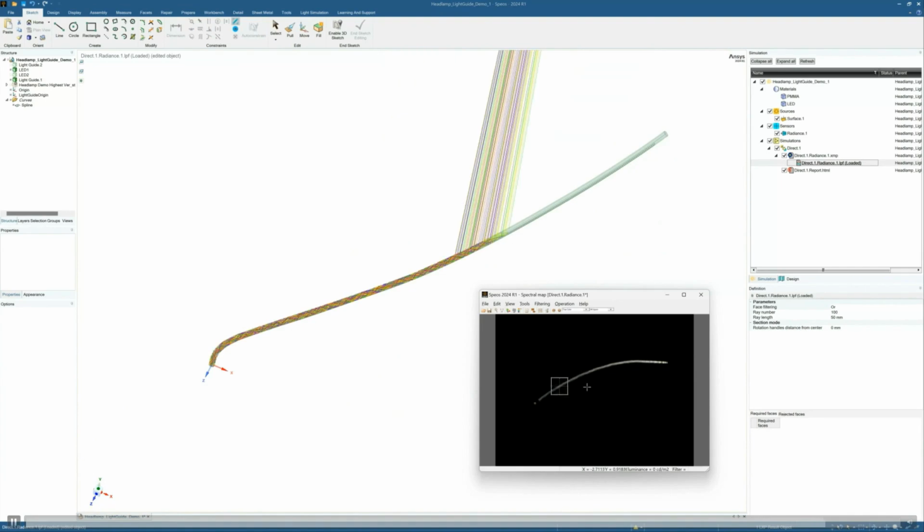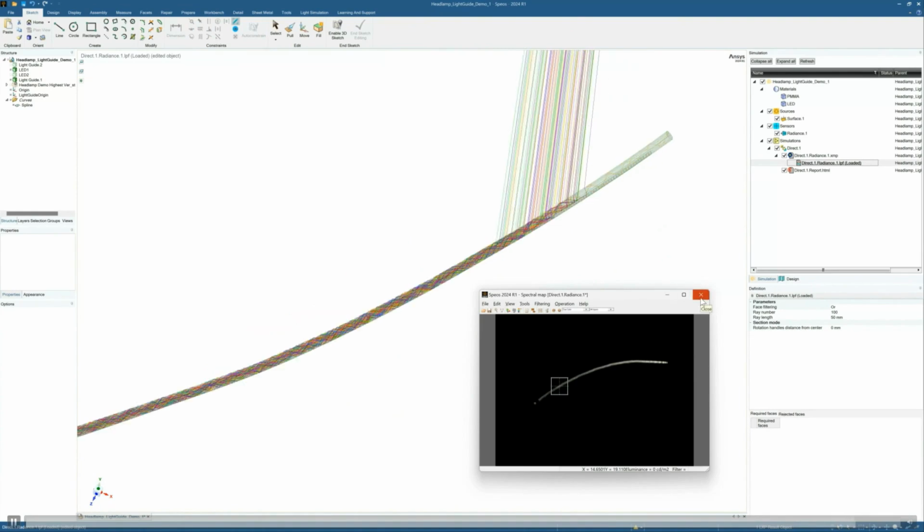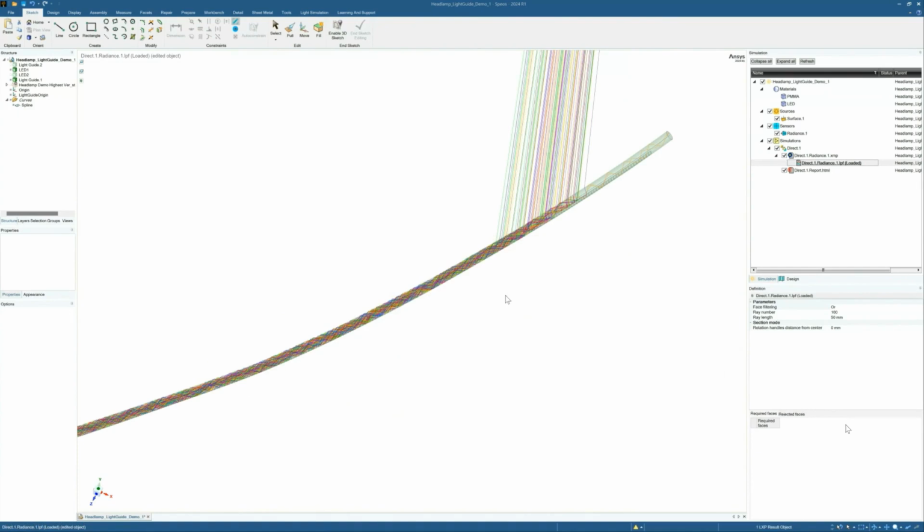You are also able to change the ray numbers. There are a lot of rays being shot through the system right now. You can pare that down to just a few, or change the ray length as well. So I think that's it for that. That's what I was saying right here in this section: this ray number and ray length is just for your imaging purposes, just like how that source was. It doesn't have an actual impact on the simulation itself because it's still shooting through 2 million rays. But if you wanted to get a better idea of what was going on and not have an entire mess in here, you can pare these down.